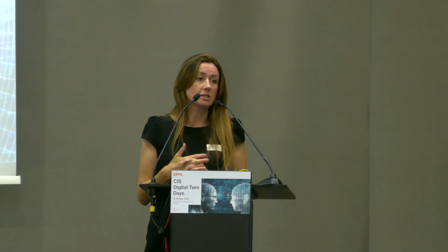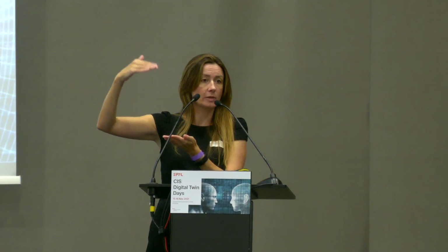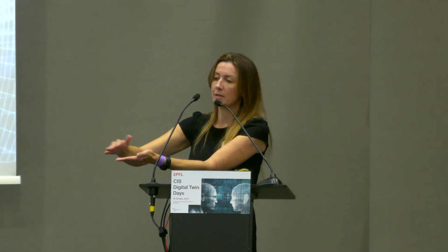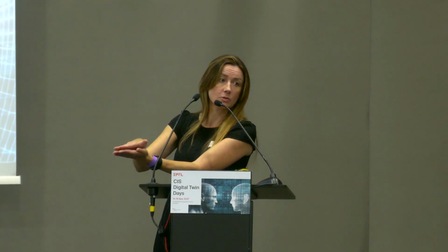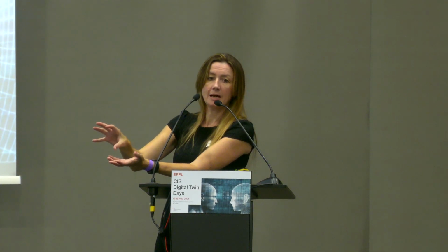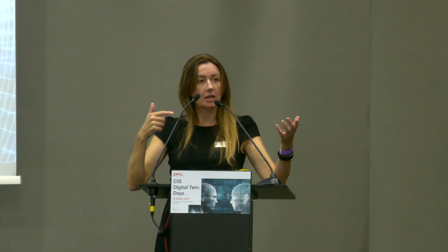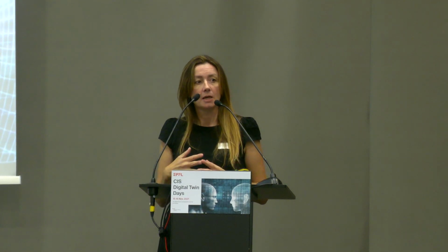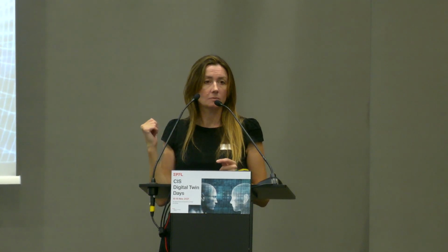So the strategy that we use for adaptation was to create a component library where we have multiple copies for each component. So you could imagine, panel number 3 on the wing. We ahead of time have computed reduced order modeling components where it's pristine, 10%, 20%, varying levels of damage. And all of those are stored in a library. Then the optimal classification trees that I mentioned, we can very rapidly take the data, classify which state we're in, grab the right component from the library, piece it together, and do the reduced order model evaluation. And so I think, can you do it fast enough to make the decision before the airplane has to turn the corner?